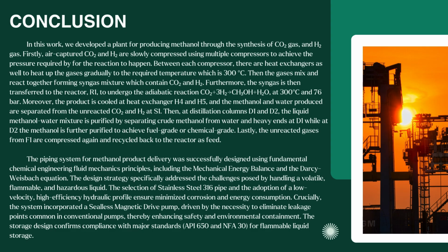Finally, I'm going to give the conclusion. This work designs a methanol plant using carbon dioxide and hydrogen. The gases are compressed, heated to 300 degrees, and reacted at 76 bars to form methanol and water. Products are cooled, purified, and unreacted gases recycled.